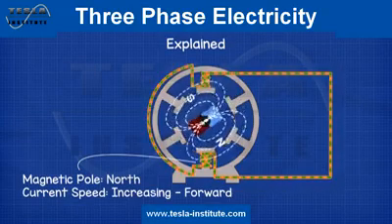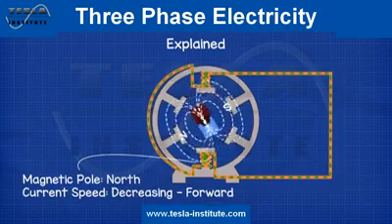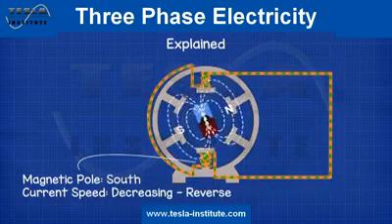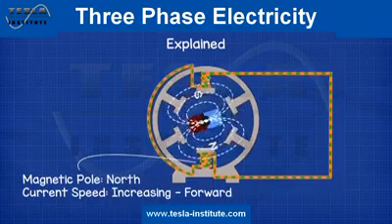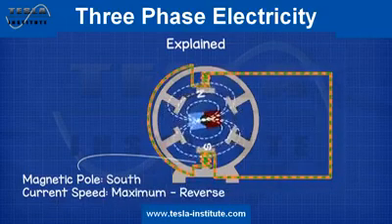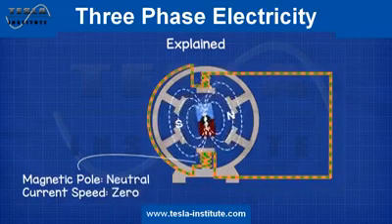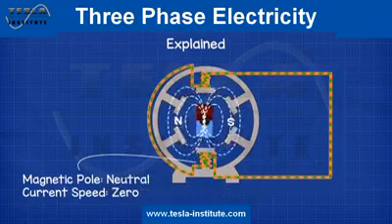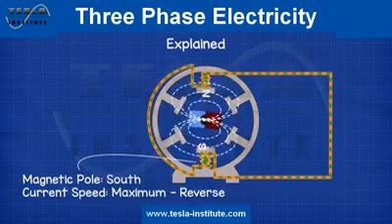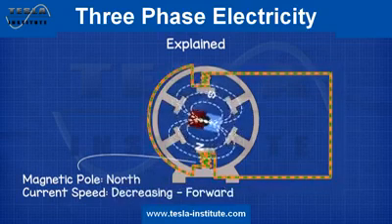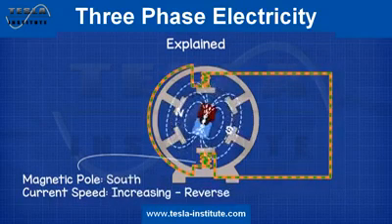So as this field rotates, the coil will experience an increasing intensity of the magnetic field's positive half, and during this increase, the free electrons within the copper coil will be pushed and begin to move faster and faster in one direction, up until it reaches the maximum point of the magnetic field. Then, as the magnetic field decreases, the flow of electrons will begin to slow all the way until it reaches the neutral point where no electrons will flow.